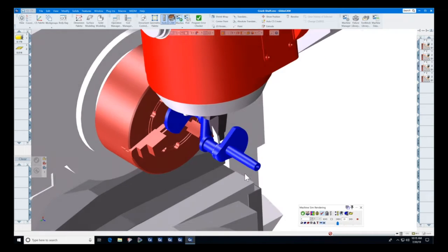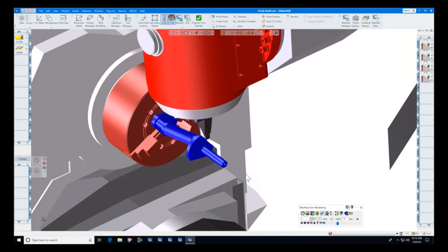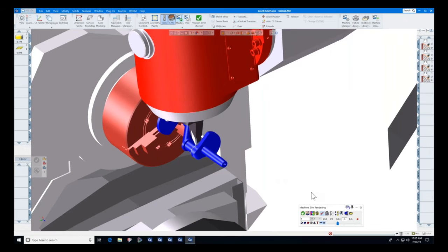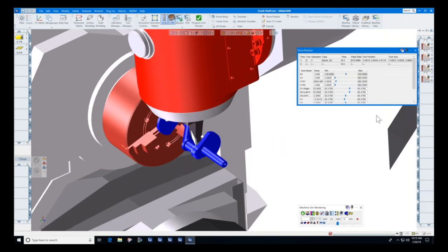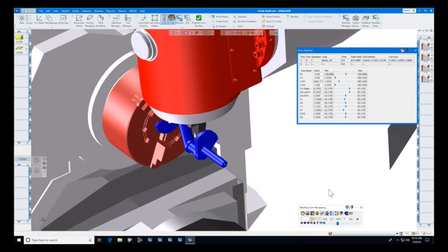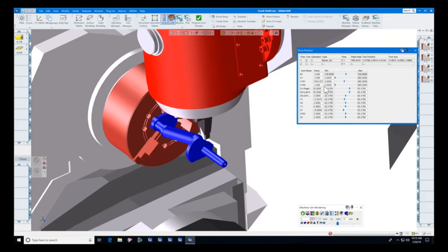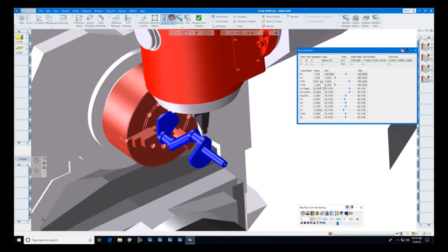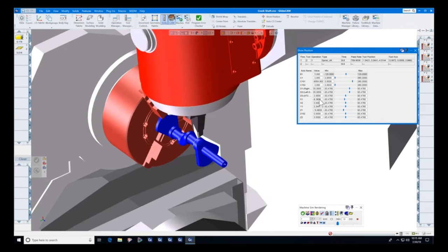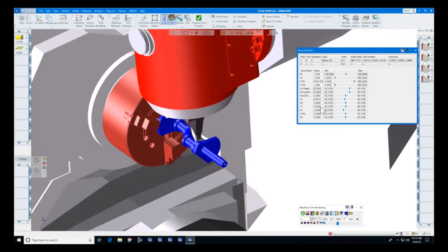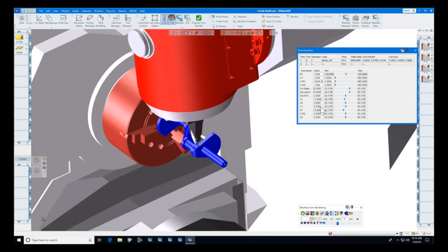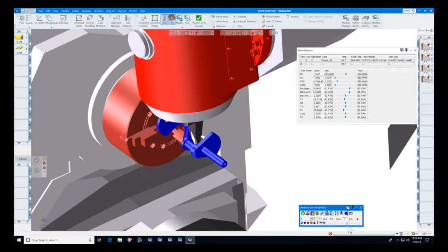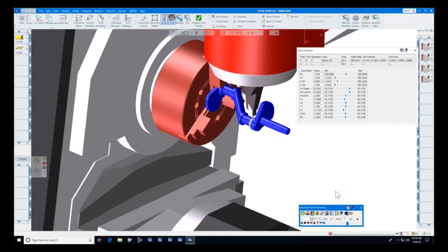And as you can see, there's quite a bit going on when you're doing eccentric turning. The tool not only has to follow the eccentric, but the y-axis has to maintain the rake angle of the tool. So here we're going to use our little button here that says show position to see exactly what's going on. Which axes are moving while this action is turning? Well, obviously the c-axis is moving. The x-axis is moving to follow the eccentric, and the y-axis is moving to maintain the center line with the surface. So here we have 4 axes moving at one time. I'll speed this up so we can get through and look how we transition over from one to the other.